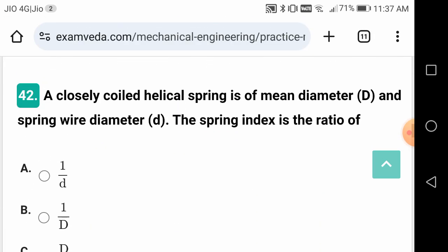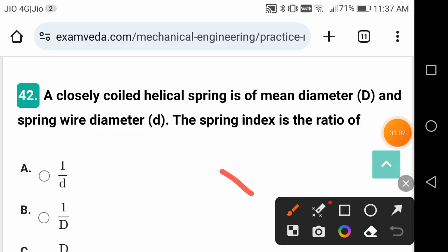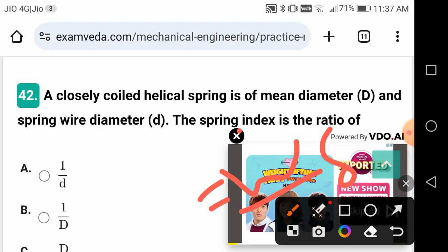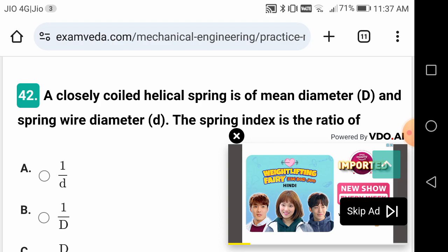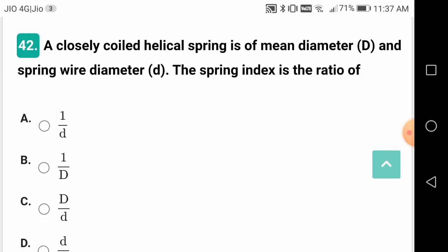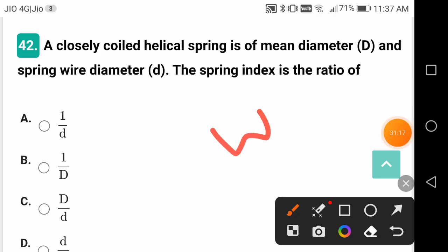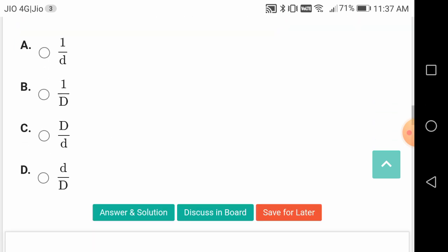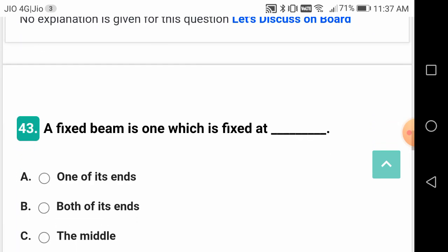And the load per deflection, W by delta, has got another name, friends. It is called the spring rate, that is, load per unit deflection. It is given by K. Load will be in newtons and deflection in mm. Normally, for very small deflections of springs, it will be newton per mm.